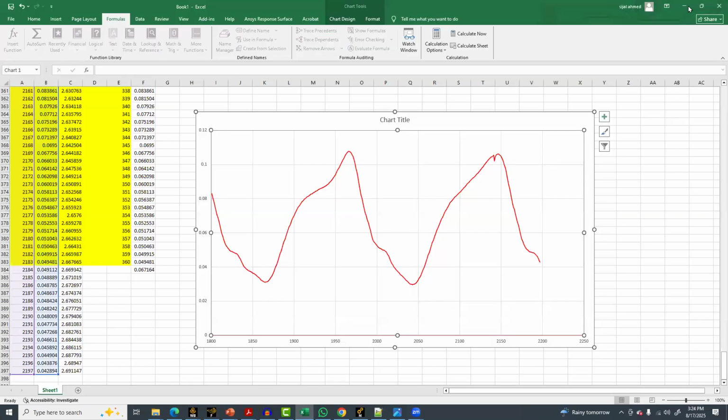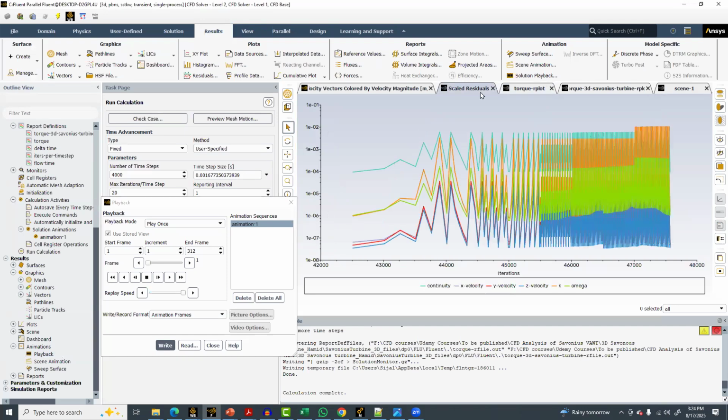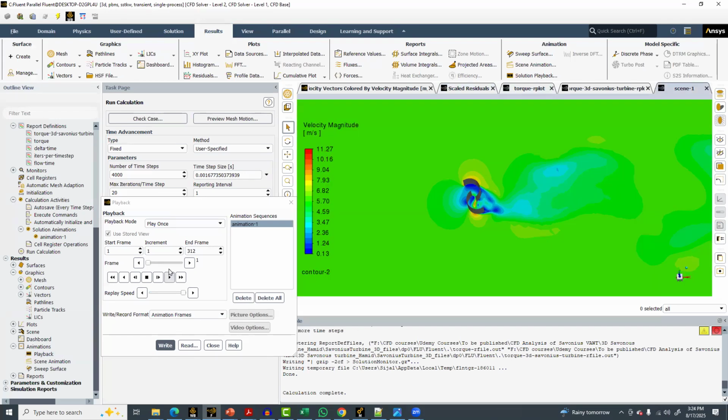The best, recommended way, as given in high quality journal papers, is that you should record data for at least the last 5 cycles. The first 5 cycles will be run and we will not monitor any data, and the last 5 cycles will be the data that we monitor and then average out. So if you take a look at the animation, you can see it like this.